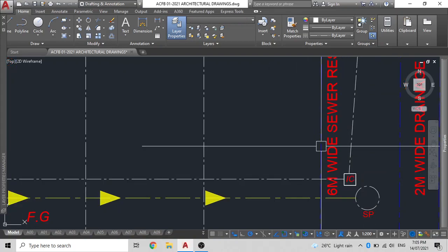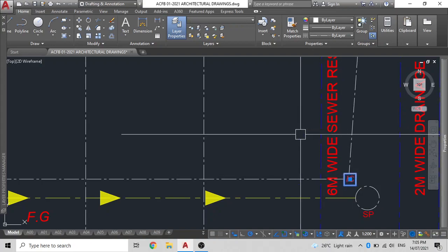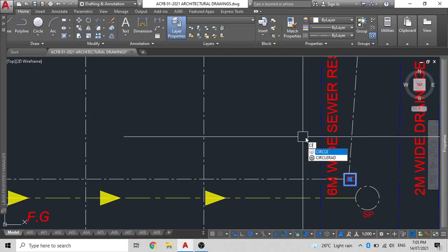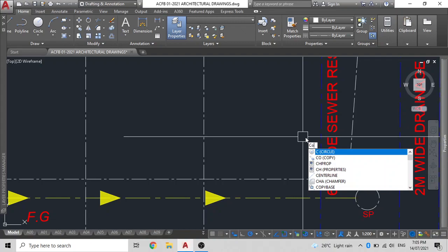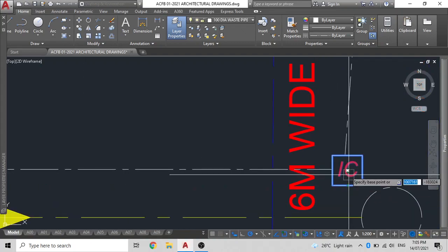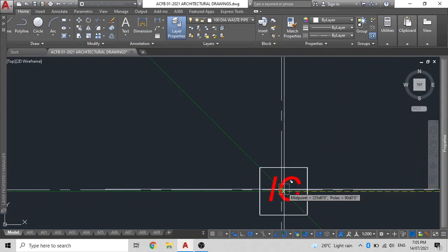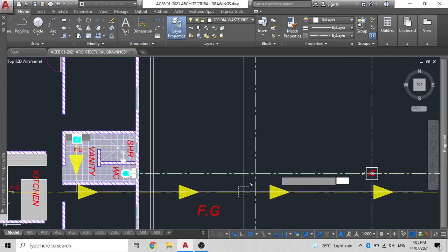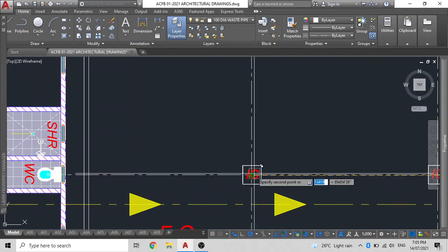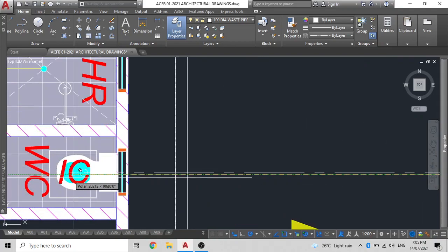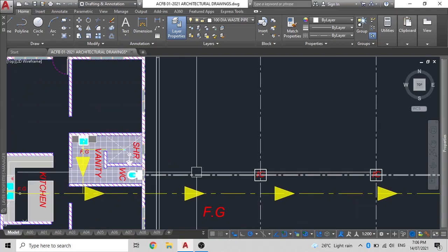You can be smart here. You don't have to copy everything that I'm doing. You can do it your own way, but remember a pipe length is 6 meters, so I'm using 6 meter centers so that you get more use out of your pipes and you don't have to cut and throw them away. If you wish, you can have one right outside, but that's not really important.